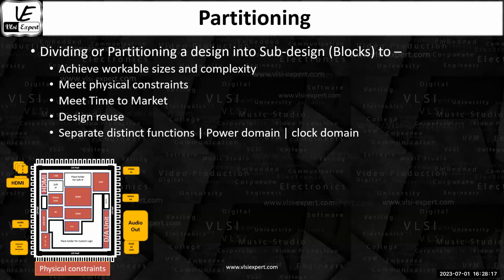Then there is a concept of a clock domain and power domain, from a functionality point of view. Power domain in the sense that, in your circuit, from a power point of view, you say one portion of my design I will run on 1 volt, another portion I want to run on 0.8 or 2 volts, anything.